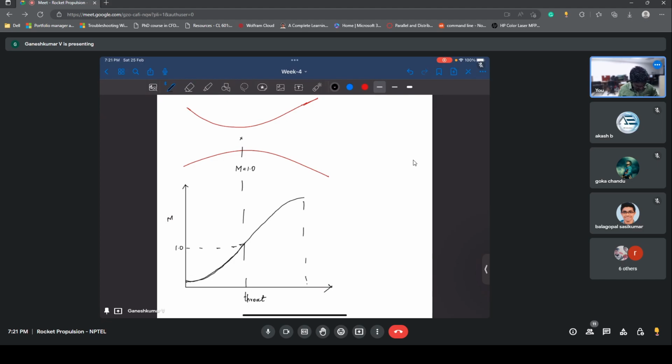So this is at the exit. This is the fully isentropic supersonic flow, which is the ideal case. It happens only at the desired altitude for which the nozzle has been designed. But let's say you haven't reached Mach number equal to 1 at the throat, it's going to reduce. It's not going to reach supersonic. So only when there is supersonic flow will you have shocks.